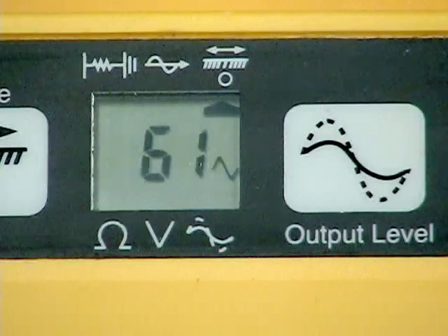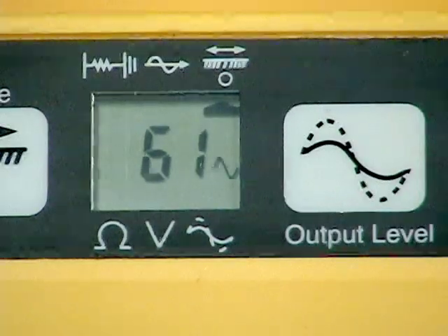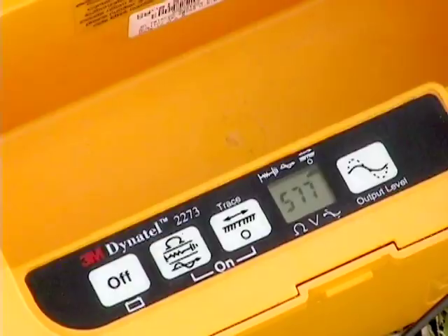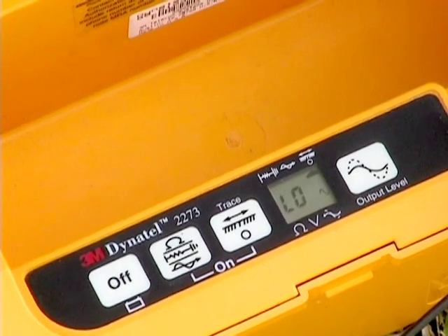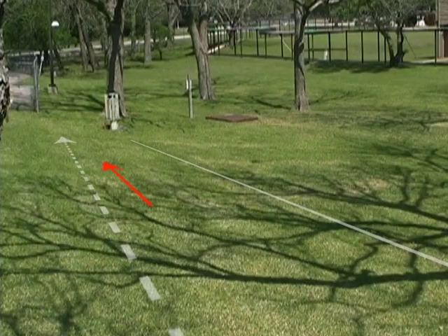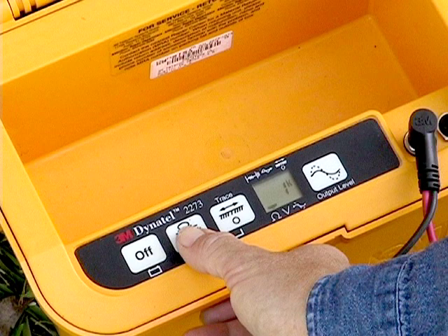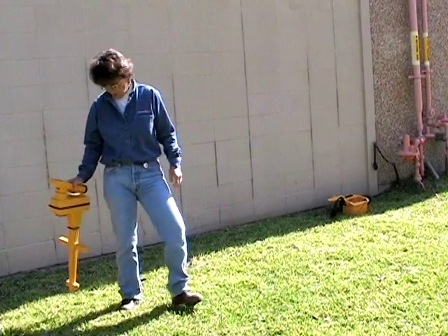Current measured by the receiver on a suspected target conductor. If Low is flashing alternately with the frequency, the signal path circuit is incomplete or inadequate. The far end return to earth may be missing. Verify that there is a return to earth on the far end of the target conductor and then measure the signal path resistance again.